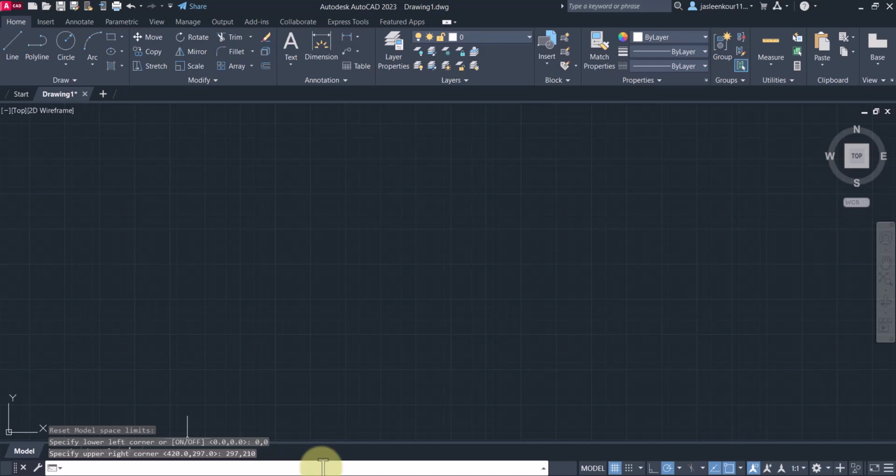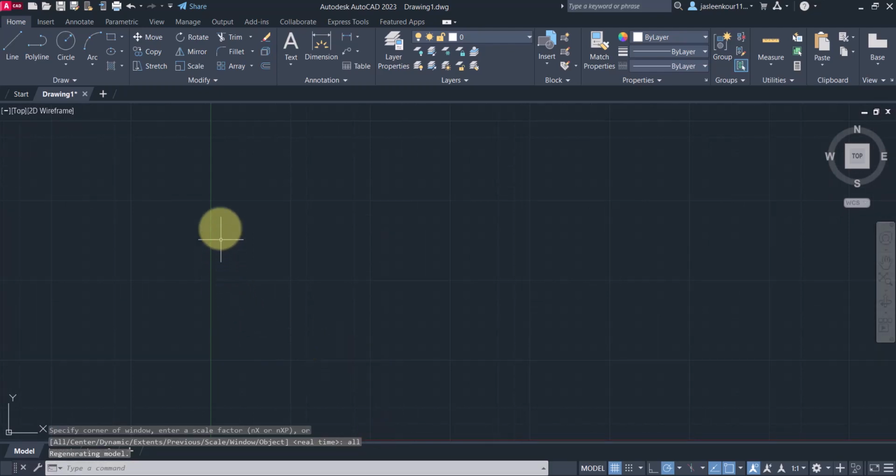Next I'm going to type the zoom command. This zoom command is used to zoom to the particular selected limited section. So I'm typing zoom, and here I want to enter all. So enter all. Now you can see the green color shows here. This green color shows the starting point or origin point of the screen. So you can check clearly.